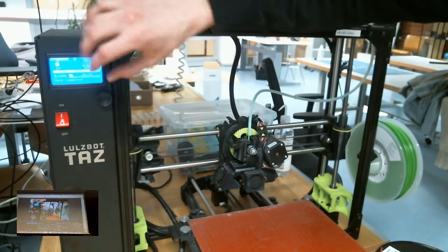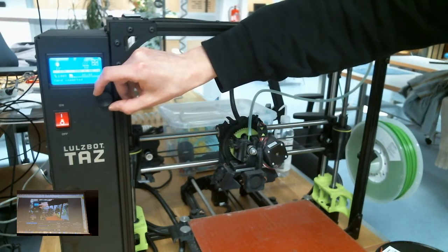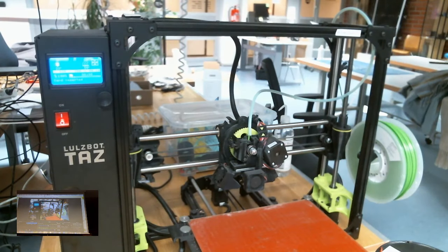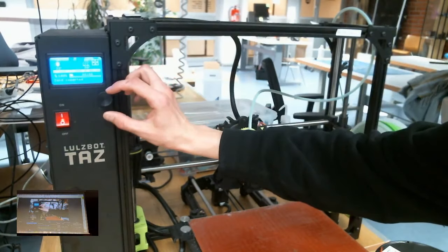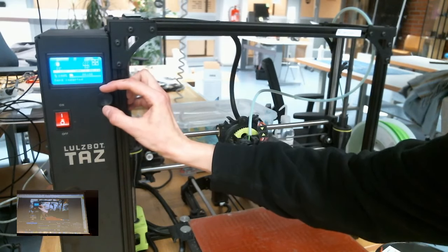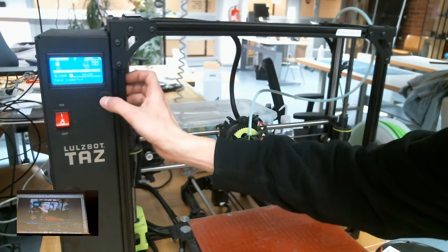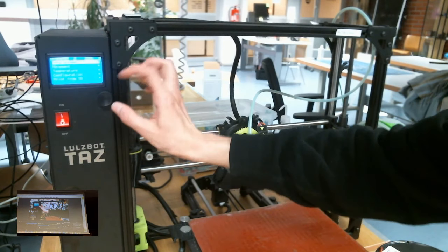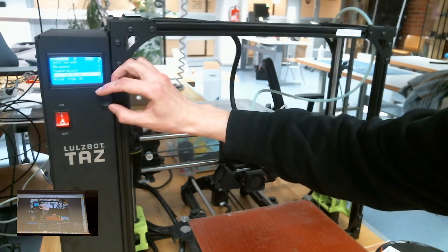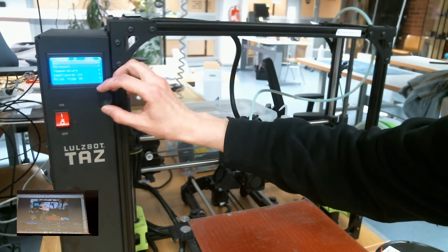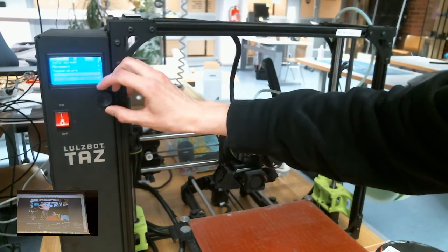And this is the user panel. The user interface you can control by using this kind of encoder, a knob encoder, which also has button functionality. So there are two things that you can do with it. One is you can turn it in order to navigate the menu elements, and the other is when you press it, it acts as a button. Here you can see multiple menu items, and you can navigate those by turning the encoder.